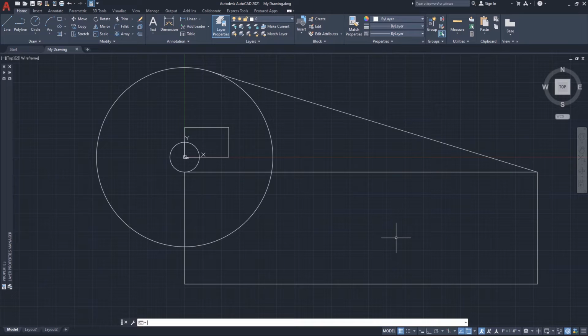In this instance, we will use the Dimension Styles Manager to make our desired changes. In the Annotation panel, on the Home tab, to the right of the word Annotation at the bottom of the panel, select on the pull-down arrow.